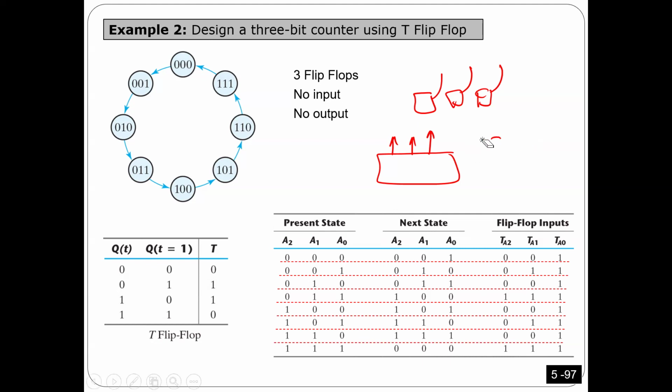For example here, I want to make a 3-bit counter. So as you see here, based on the description, it's easy. You can draw this one. Look here, guys. Here I'm going to start from 0, 0, 0. And then every clock will make a transition. So after 1 clock, I'm going to get number 1. After 1 clock, I'm going to get number 2. After 1 clock, I'm going to get number 3, number 4, 5, 6, 7, and then I go to 0 again.